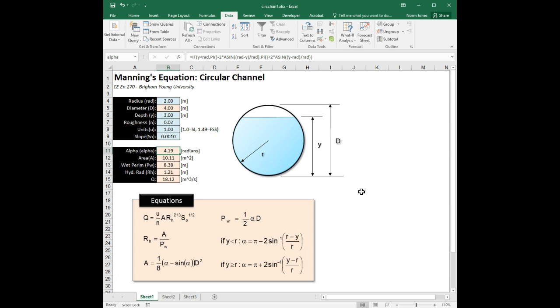You do a hydrological analysis and you say, okay, we need to pass through 50 cubic feet of water per second. And so your job as an engineer is to build a channel that is large enough to hold that. So what I'm trying to say here is it's not too common that you're given everything but Q and all you have to do is solve for Q. Typically, you're given Q and you really need to solve for the diameter.